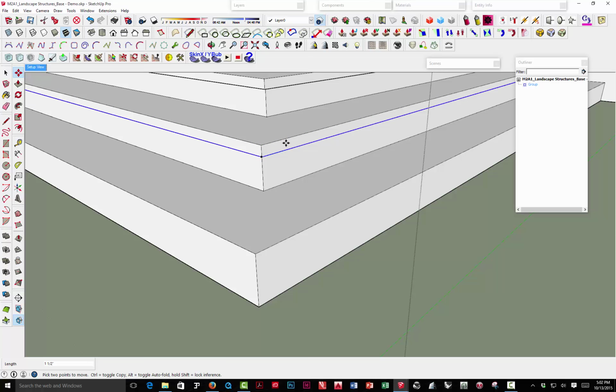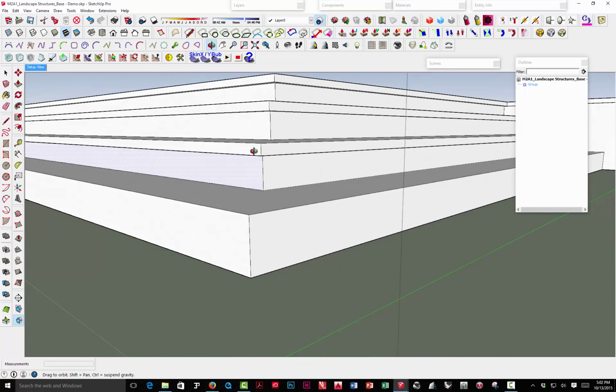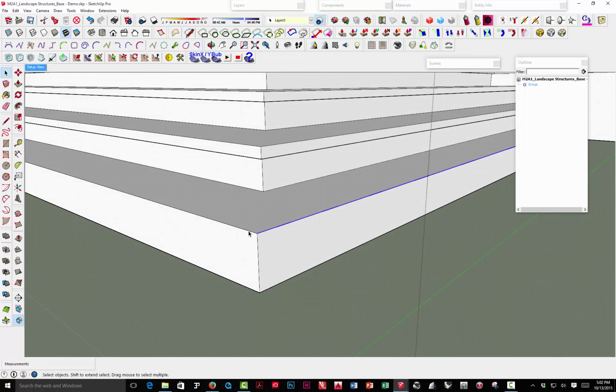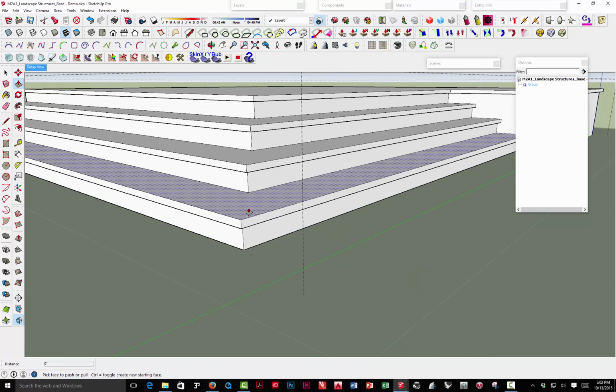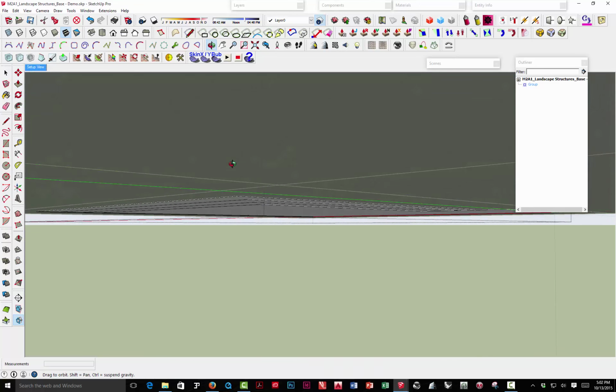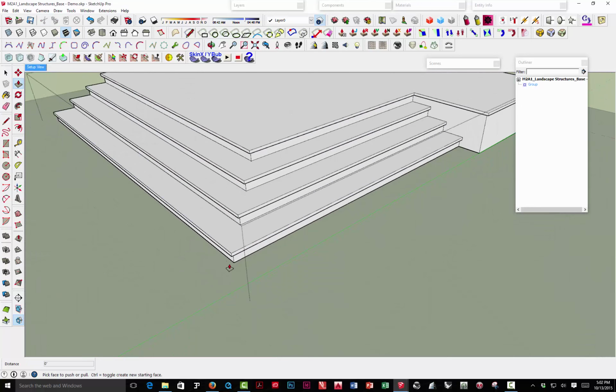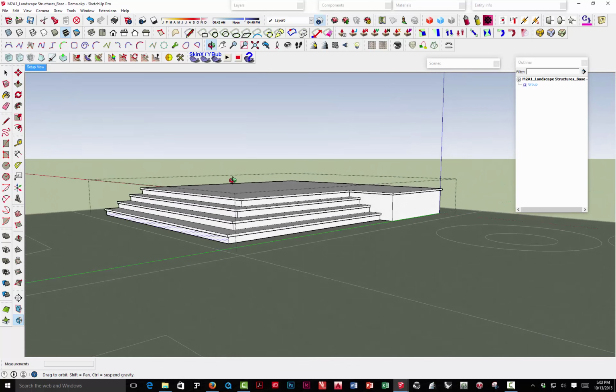Now, out here, you can move it vertical. You get the blue axis. Everything's fine. But it's also possible to move it off that here. On the corner, it's impossible. If you move down this line, it's always going to be aligned. So use that as a reference point. Go to push-pull, double-click. It's done. Space bar to get the select tool, shift click, move, control. I'm going to use the corner, 1.5 inches, push pull, double click. Okay, so that just adds that little edge, 1.5 inches all the way around, and that's exactly the kind of detail we want on that deck.